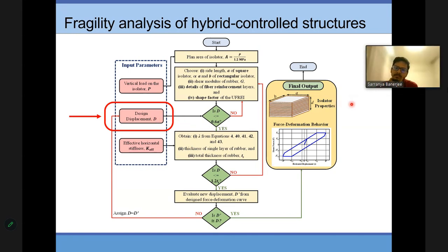You can use equivalent damping and equivalent stiffness. But if you have a TMD, well, the wind force will also be somehow simplified. I mean, the designer cannot do time history analysis. So it's better to have a simple procedure only using the design spectrum or static wind force.